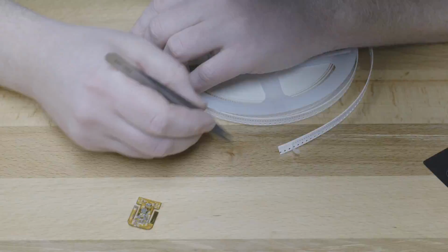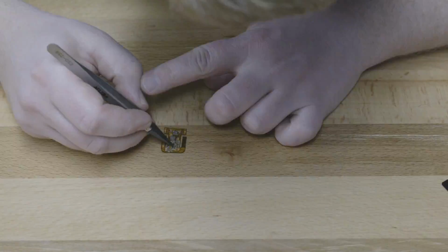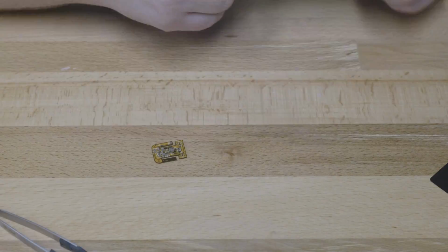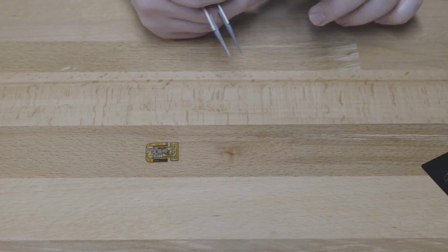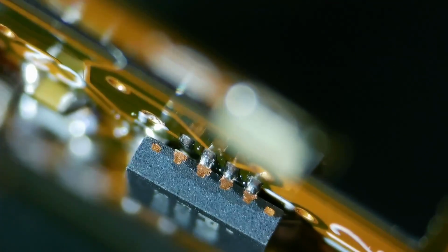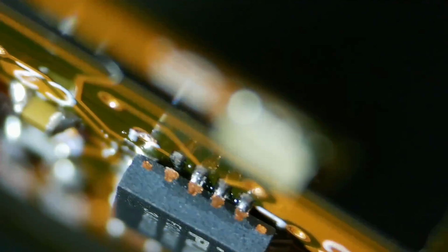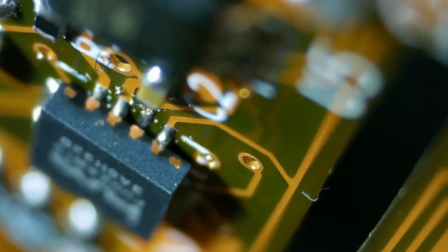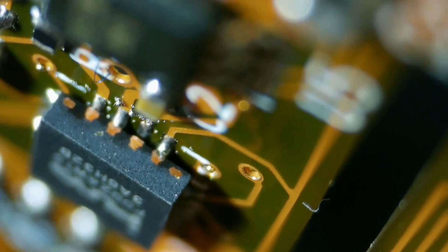Now rinse and repeat for the other side of the board, and we're done. Well, almost done. I had a couple of minor issues to fix. For one, there was too much solder on some of the components, particularly on the thermal pad under the microcontroller, and this caused some of the pins on the microcontroller to lift up and not connect. I removed this part with a hot air pen, removed some of the solder with the soldering iron, and popped it back down.